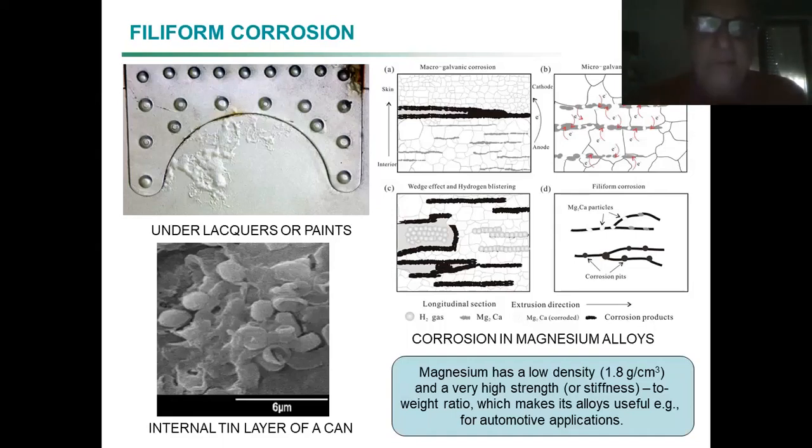This is important to remember. If there are local anodic and cathodic parts, then this part of the metal behaves as a dipole. If there is a dipole, that means that some electrical current can pass through the metal, provided that a potential is applied. So if I apply a potential, then some current passes.